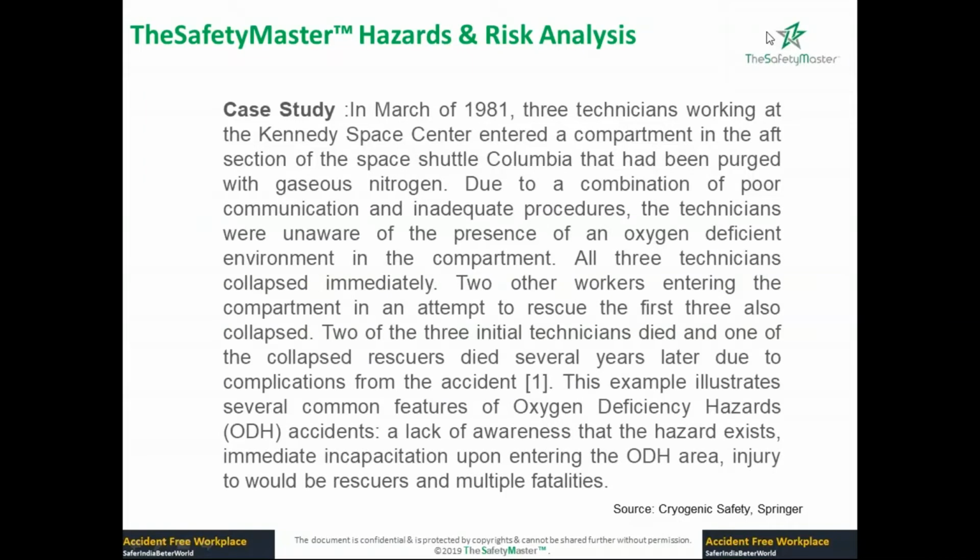The first 2 went inside the chamber and collapsed. The third one entered to check what these 2 were doing, and the third one also collapsed. This example illustrates common features of oxygen deficiency hazard accidents: a lack of awareness that the hazard exists.